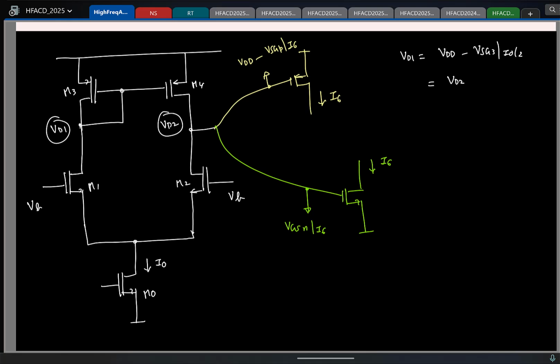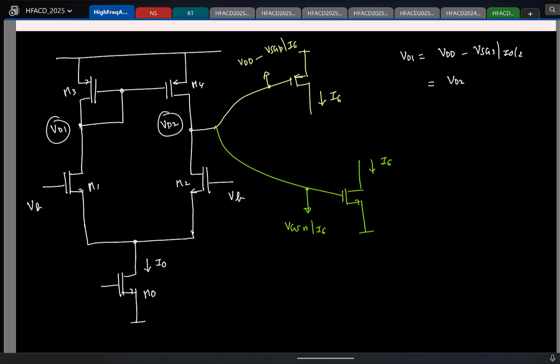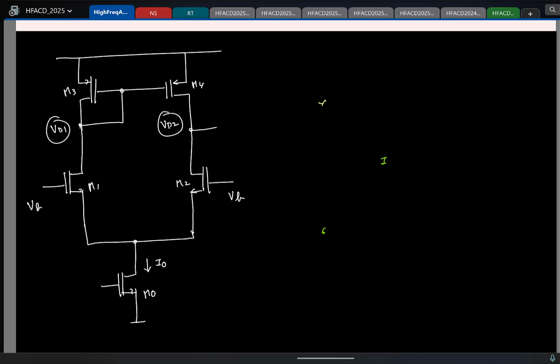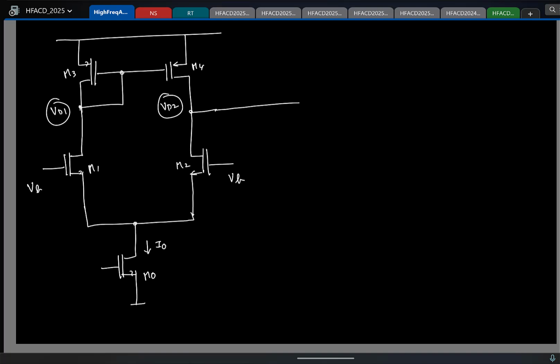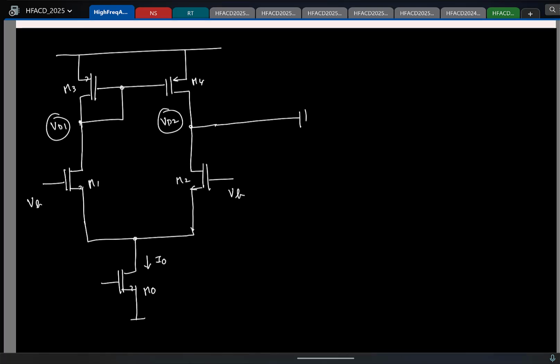So then, now it's clear. I have to have a PMOS input, so let me mark that. I'll draw a PMOS common source. Let me call this M5. And of course, at the drain side, I should ideally have a current source. How will I realize this current source here now?